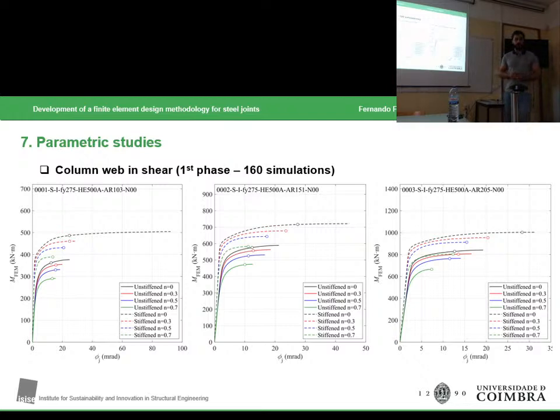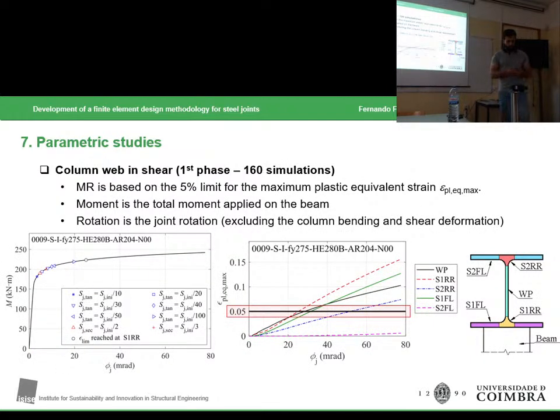In slide number 44, just one slide actually, this 5%, yeah, I've tried to read part of the standard, and part of the work that I'm doing is also related to this, and I also want to question it. My question here is, which part of the cross-section do you consider is the most relevant? Because I see you have several curves as you took several parts of the cross-section. Which part was crucial, either with compression, tension, or shear? And how did you take this value? Did you take the average, or did you take the first incidence of the 5% plastic strain occurring in those regions? It's the maximum. So the peak, whatever value when it reached 5%.